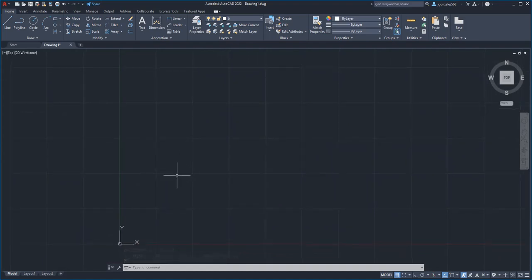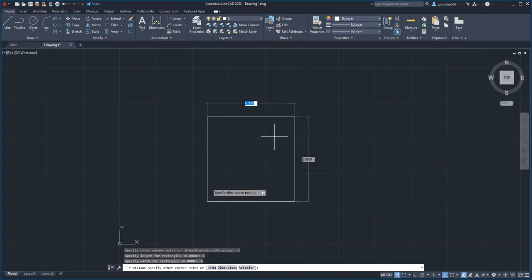Now I want you to make a rectangle at 6, 3. 6 by 6 rectangle at 6, 3. So here we go. So the point 6, 3, enter. Now it's asking for, you can eyeball it, but I want you to just click dimensions and choose 6 by 6. So now as you can see, it wants to know where exactly, because I have the corner selected as 6, 3. So I'm going to choose over here. So the upper right option. Okay. So 6 by 6 dimensions rectangle at 6, 3 when you use the rectangle function.